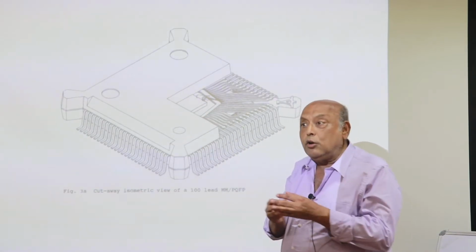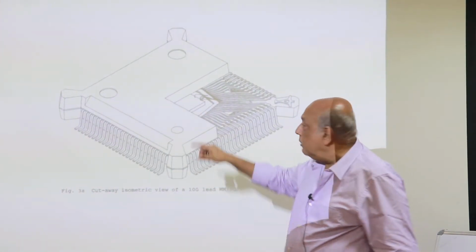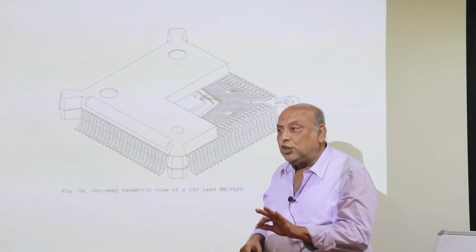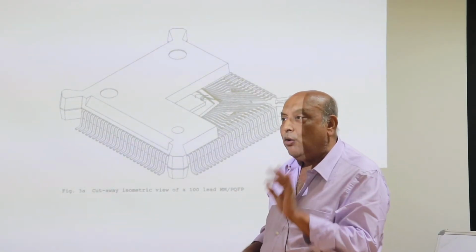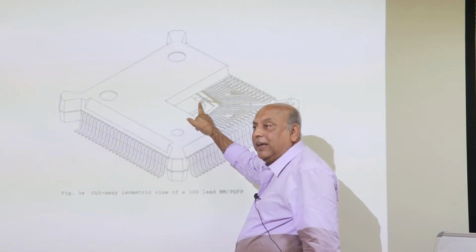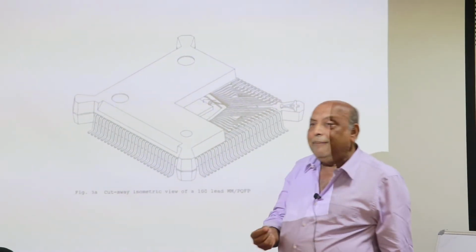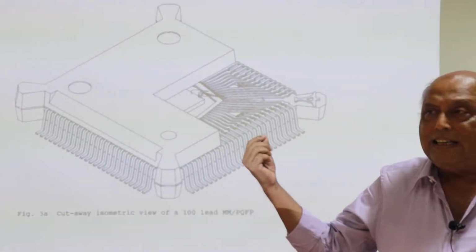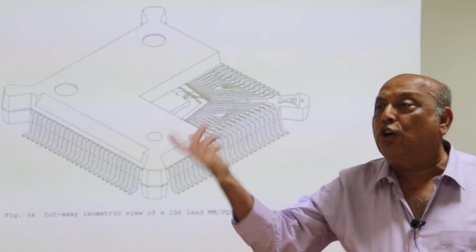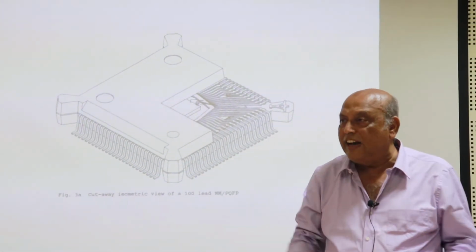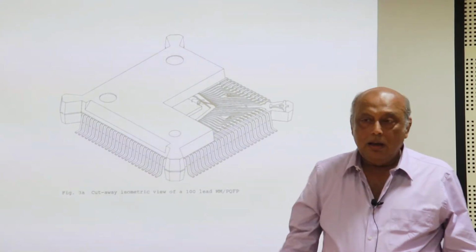The one I was talking about, the low resistance, remember? I solved the problem by putting a plane underneath there, and I bonded them to make sure the resistance is very low. So there may be hundreds of grounds here, and all of them are 125 micron. They may be 0.01 divided by 196, so it will be 0.001 ohm times 100, nothing. It's a very small drop. Next file.